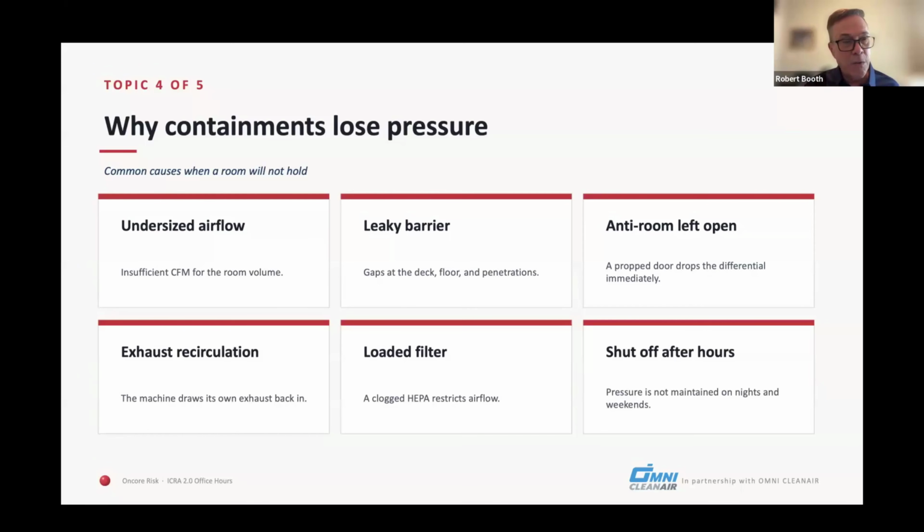I hear, well, how am I going to do that? If I cover it up, it's going to be bowing out and I can't get it isolated. I know that's a problem. You have to work that through in the pre-planning stages of the project. How are you going to isolate that HVAC system? Big projects, they're demoing a lot of that. So sometimes they can cap it off, but then that overpressurizes other areas. And that's a whole other topic altogether.